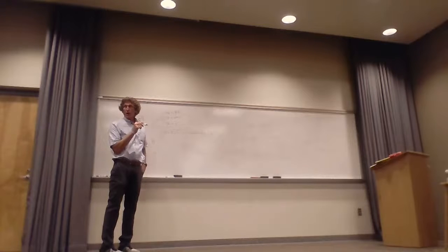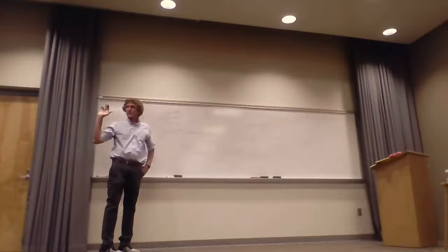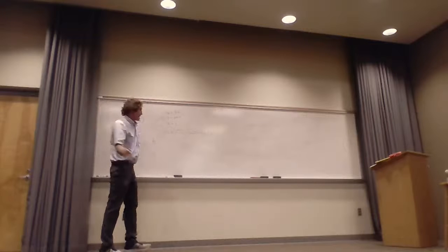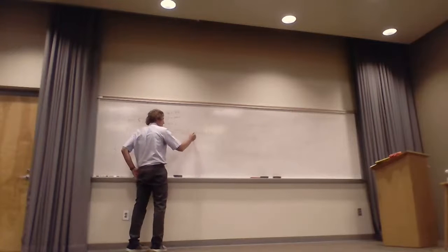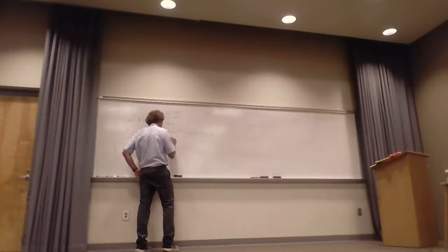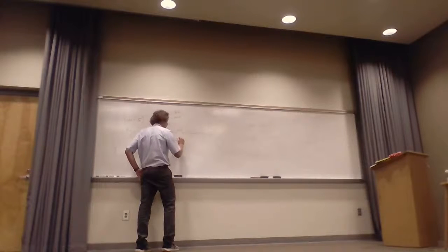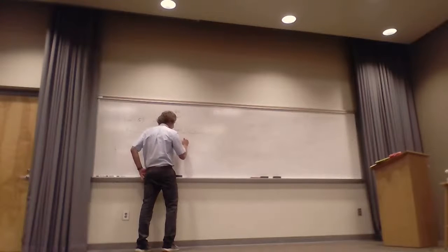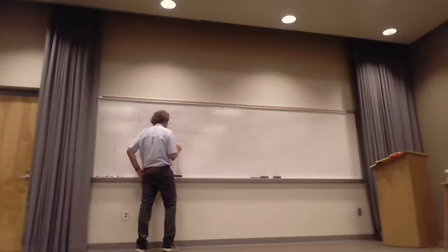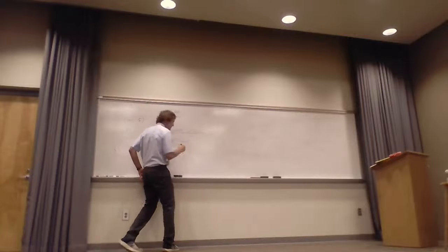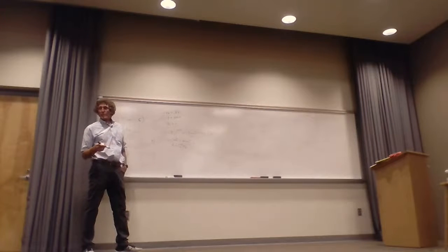All right, before we get the intrinsic impedance, let's get a few basic parameters. How many of you know what the frequency is, looking at that? How do you get the frequency, anyone? You look at the coefficient of t. That's omega. So omega is equal to 2 pi f, and that's 2 pi times 10 to the 9th radians per second, or f is 10 to the 9th hertz. These things are assumed, but I want to go through it.